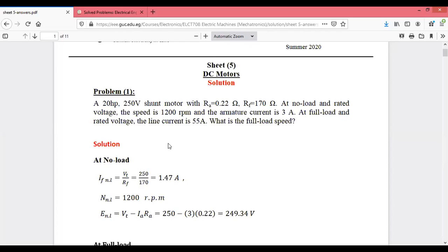E means the supply voltage that we are giving, which we have just seen in the PPTs for our DC machine. In that we saw we get the equation for voltage by using KVL for the DC shunt motor. How do you get it? V equals Eb plus IaRa. Converting that equation for Eb, you get V minus IaRa.